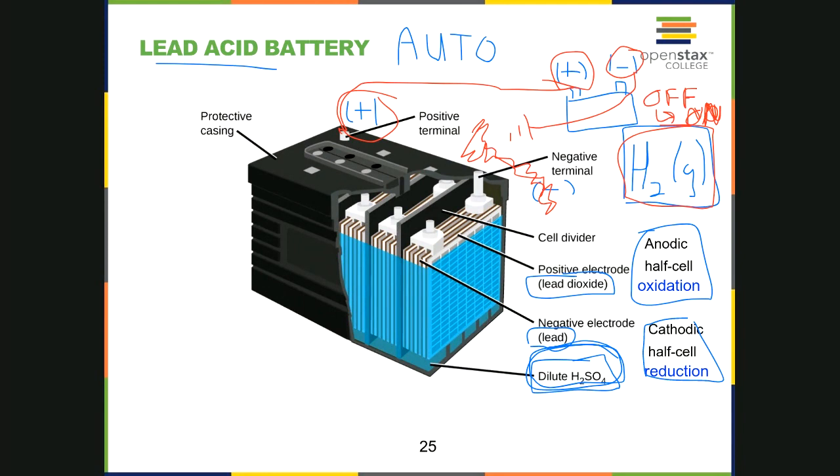You could try to start it with the cables connected, but that is not as safe. Okay, main thing is to avoid connecting the negative from the donor battery directly to the negative on your battery as far as having a risk of having an explosion. So that's your safety message for the day, all the while maintaining social distancing somehow.